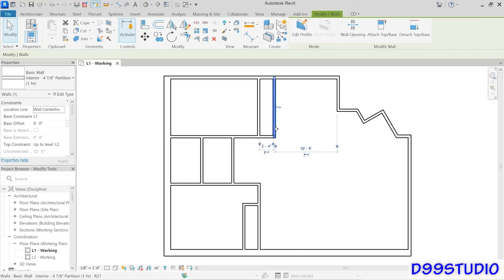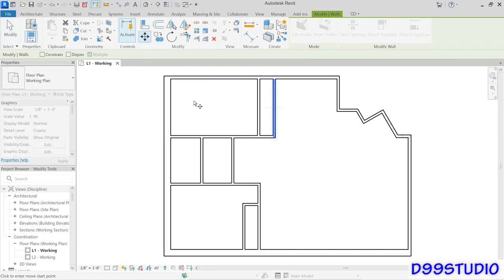So I'm going to keep the wall selected, go right back to Move. This time, it goes right to the second step of the Move command, which is basically saying how far and where do you want to go, because it will assume that I'm trying to move the element I already had selected. So you can do the selection either way. I actually prefer this way. I like to make the selection first. I think that's a little bit more convenient, but it really is up to you which method you use.